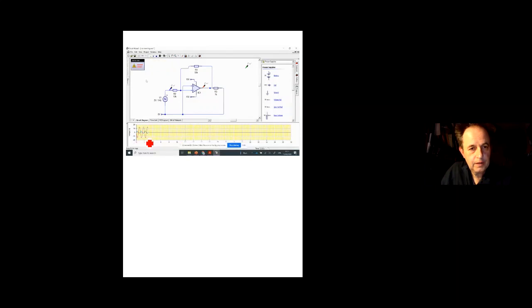Okay, there we go. Blue one is the one, small one coming in. Notice the red one, which is the negative, is inverted. So it's a negative graph. Okay, changing the resistance value of the feedback resistor here, so a much larger gain. And then we've got clipping happening again.